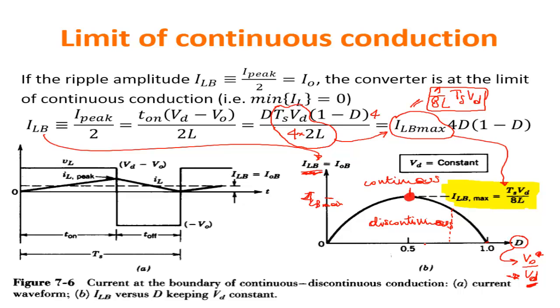And in a typical DC buck converter, it is very common to go continuously from continuous conduction to discontinuous conduction, as a function of the current that the circuit is absorbing, which means the power that the circuit needs.